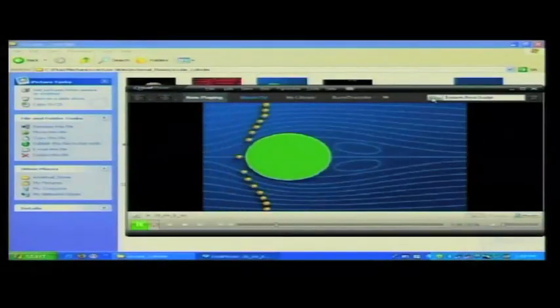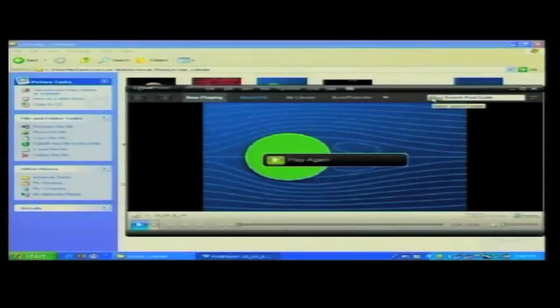And what is the consequence? Whatever we showed as a visualization example, let us see as a simulated example. You see two counter rotating eddies formed at the back, in the low pressure region or the wake side of the cylinder. We are talking about still low Reynolds number cases.